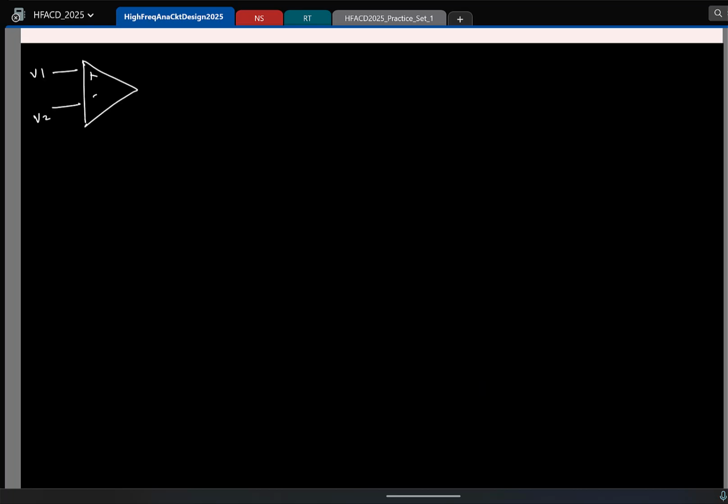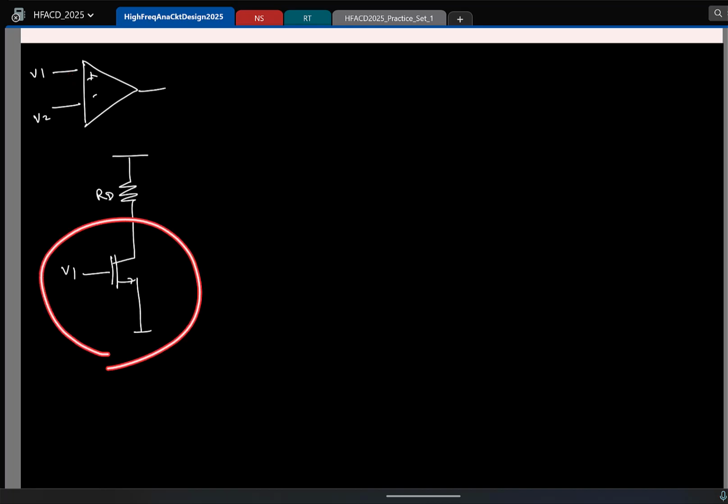great. So yeah, now we want to make an op-amp with a large gain. So which of the three configurations is useful? Common source, common gate, or common drain? Common source. So let's say we do this. V1. So here the gain will be, this is going to amplify only V1, but I want to take the difference between V1 and V2. What is one simple change I can make here so that the current here is dependent on both V1 and V2? If I connect V2 here, the current is GM VGS, GM times V1 minus V2, and we get it.